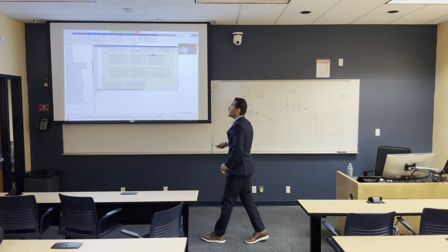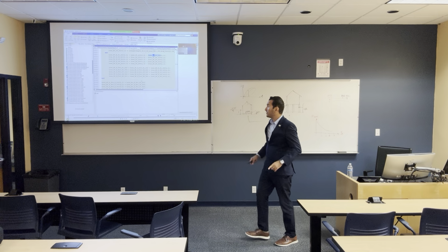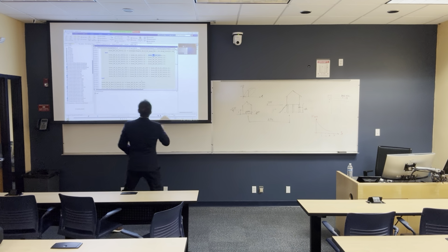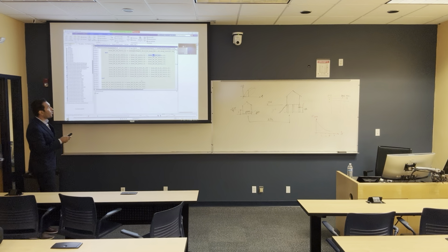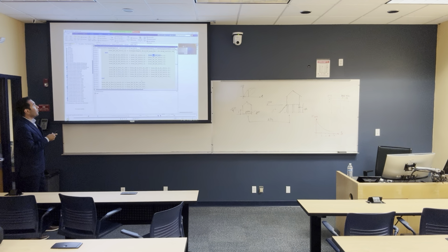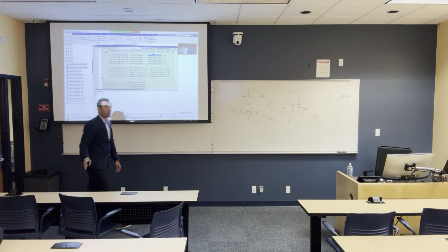If you want to calculate the total flood loss reduction for the entire community in just one number, keep accumulating these numbers one by one in this matrix or storage. Once you calculate losses for building 1, put it here. Building 2, put it here. So I'm doing a summation for the building total loss in this one. This represents the losses if you have elevated components, and this means reduction total for flood duration 1 day for 10% of the buildings.